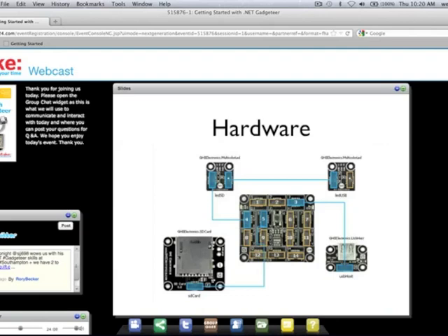So this is the hardware diagram, and again, as you can see, as we're connecting up modules, it'll only let us make valid connections to the main board. There's a sort of palette on the left-hand side where you can pull out all sorts of different types of main board and all the different types of module. So when people go about designing modules for use in the Gadgeteer system, as well as producing the hardware for the module, they also produce a software component that gets added to Visual Studio so that you can then pick those devices off the palettes and use them with the visual designer.